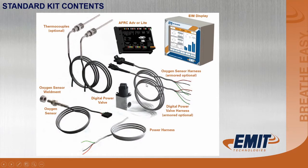Okay. This is what your typical kit is going to look like if you're just doing a standard air-fuel ratio control kit. You're going to have the display. You're going to have the module, whether it's an AFRC Advanced or an AFRC LITE. You're going to have a harness for the O2 sensors. If you've got 2 O2 sensors, you're going to run 2 harnesses. If you've got a single bank or a dual bank, you're going to run a harness for each stepper motor that you have or digital power valve. And then you're going to have the required oxygen sensors pre and post, and the thermocouples pre and post. Okay, and this one is just a power supply harness in the picture.